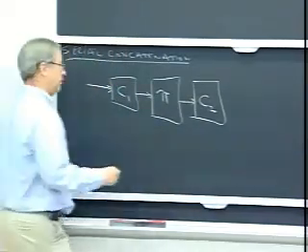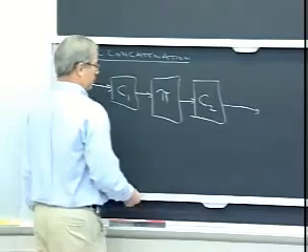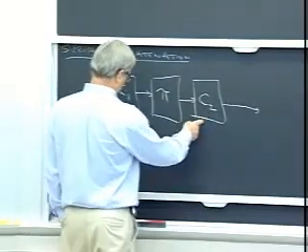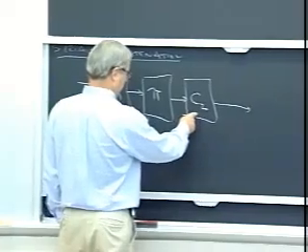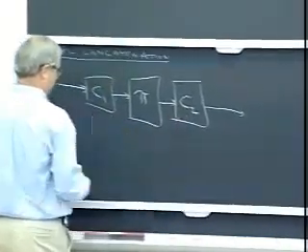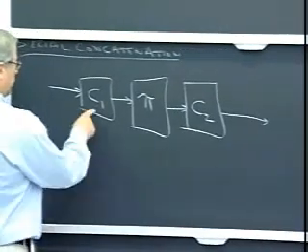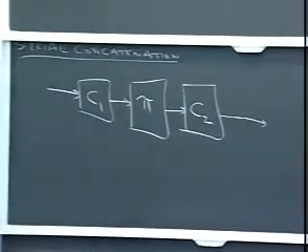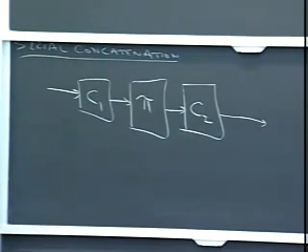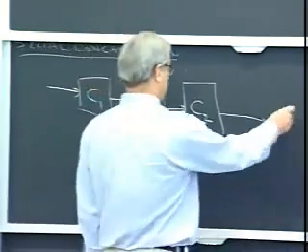that I talked about back when we talked about this. This could be a small block code or convolutional code that you do maximum likelihood decoding on, e.g. the Viterbi algorithm. And this could be a Reed-Solomon code, and the interleaver might be in there for some kind of burst protection or to decorrelate any memory in the channel out here.